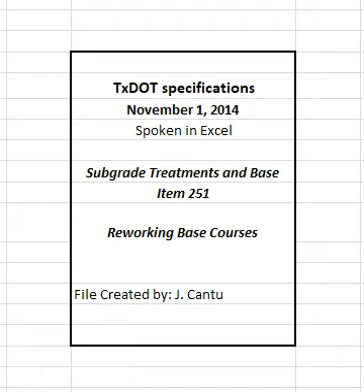2.1 Flexible base. Furnish new base material that meets the requirements of Item 247, flexible base, for the type and grade shown on the plans. 2.2 Water. Furnish water free of industrial wastes and other objectionable matter. 3. Equipment. Provide machinery, tools, and equipment necessary for proper execution of the work.